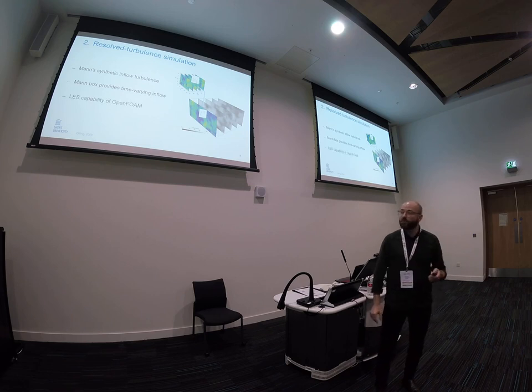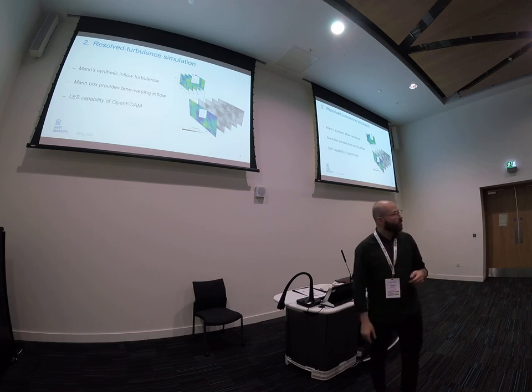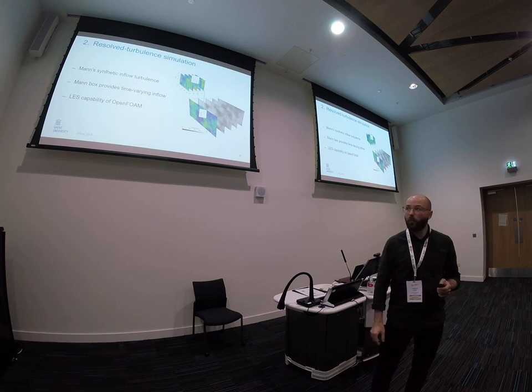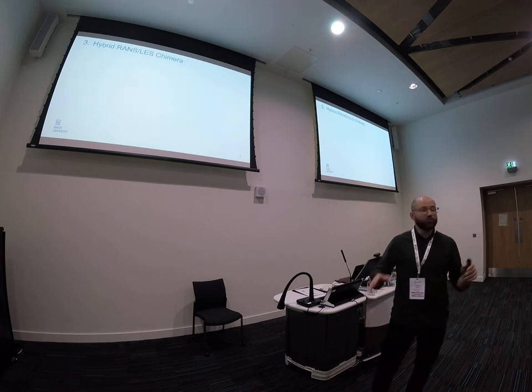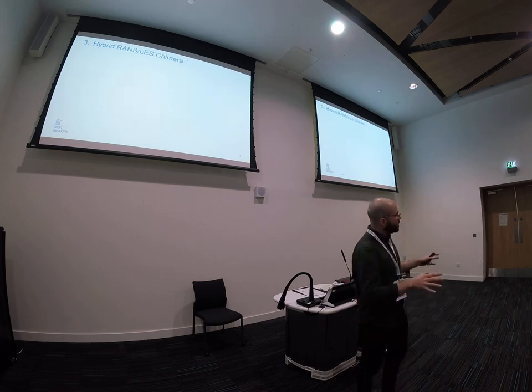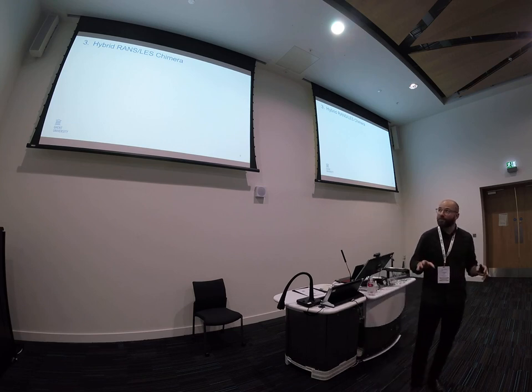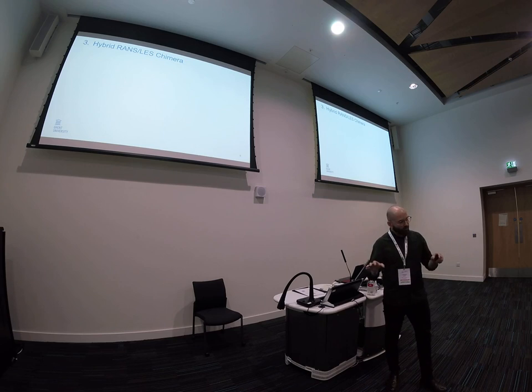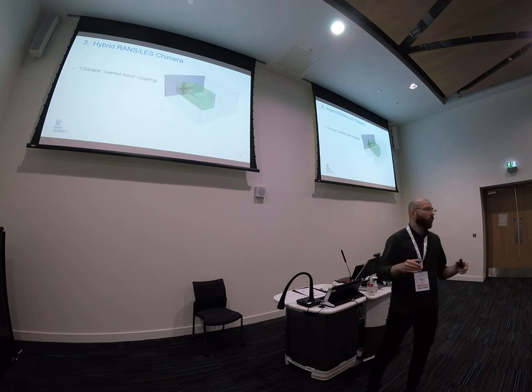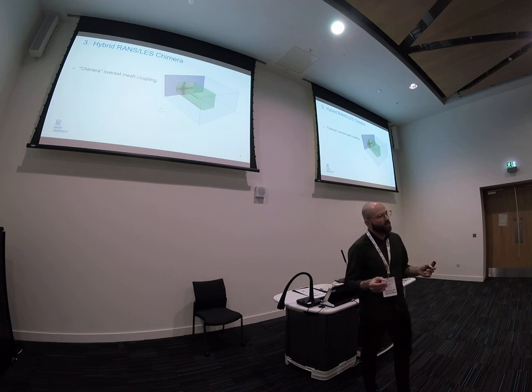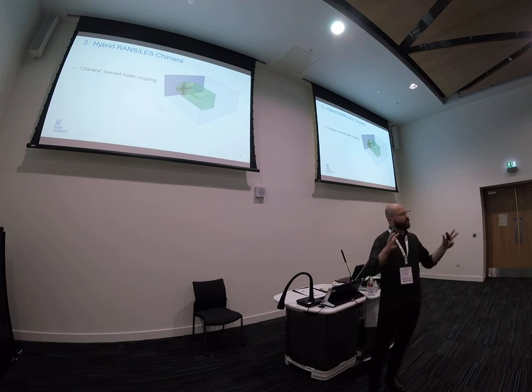And so we solve this usually with the LES capabilities that are available in OpenFOAM. In order to couple these two aspects, we use hybrid RANS-LES with Chimera. I will first focus on the Chimera approach. The Chimera approach is an overset mesh coupling technique where we take two separate meshes.